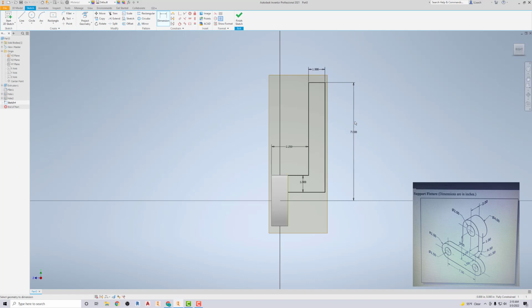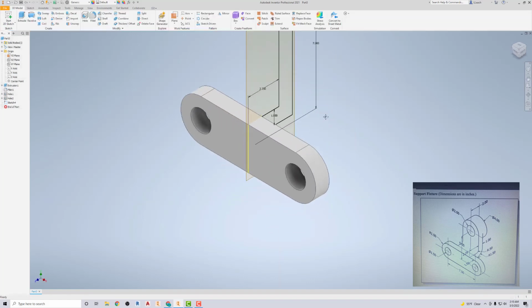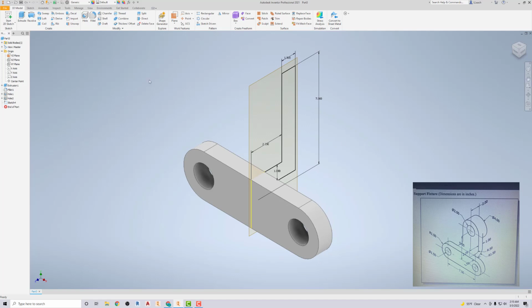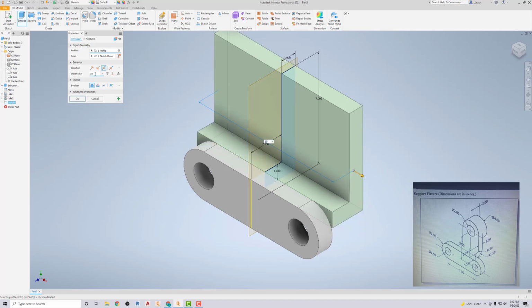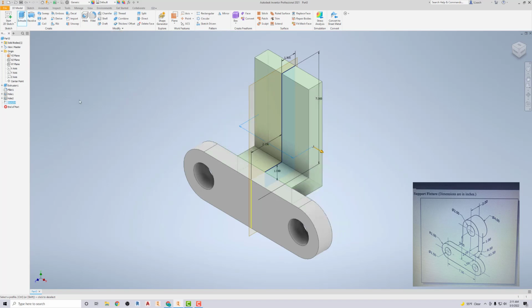So now I'm going to extrude this. Not extrude. I'm going to finish my sketch. Now I'm going to extrude this sketch here again. I'm going to use a symmetric, so it's even on both sides. This distance here, it's definitely not 10. That is going to be the same as that diameter, which is 4. All right, so now where can we go?